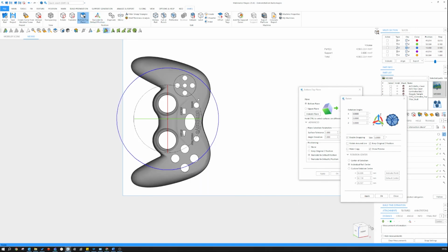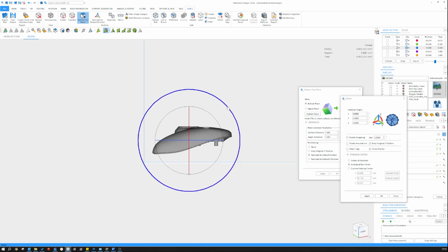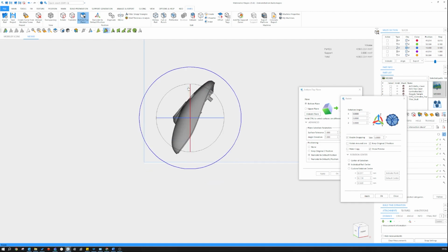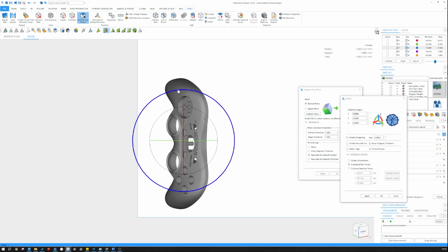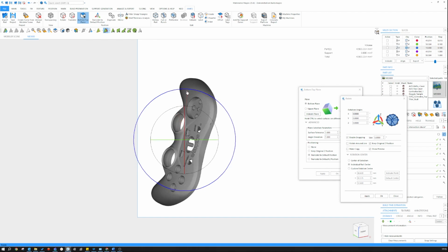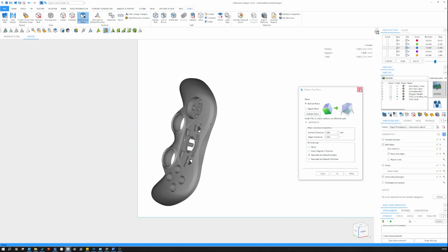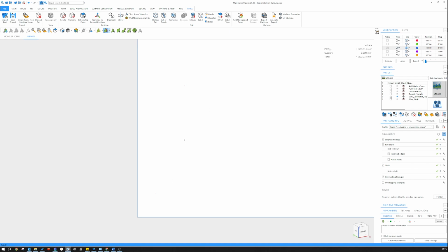Making sure the cross-section of the parts are orientated correctly to the blade is important to reduce issues such as parts being knocked off of their support structures, or to ensure that the recoater blade will not run out of resin as it passes over the parts. Using tools such as Bottom Top Plane, the Rotate tool, and Translate to Default Position, a part's orientation can be defined and the parts can be placed at the correct height on the platform, ready to build.